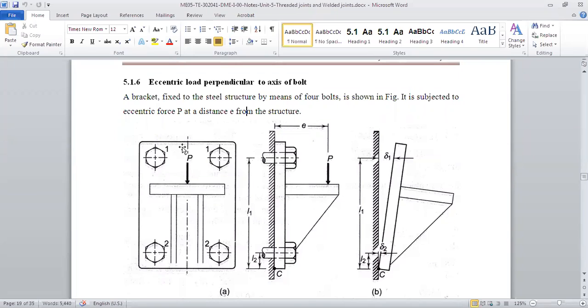As I said, these kinds of bolts will have two kinds of stresses. One is tensile. Now see, this is delta 1, which means the length is changed from L to L plus delta 1. Assume L is the length of bolt 1, then L plus delta 1 will be its new length. So it will have an extension, and because of this, stress is proportional to strain, as E equals stress upon strain and is constant. So stress is proportional to strain, so your stress will again be proportional to the distance. The more away your bolt is, the more stress it has.